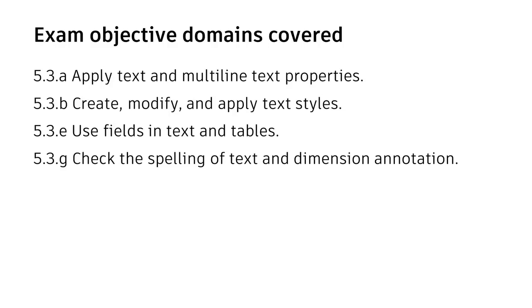AutoCAD also has some pretty nifty text features where you can leverage some of the existing data inside your drawing by inserting fields into text elements. We're also going to modify some text properties to adjust its appearance. AutoCAD has a built-in spell check and even allows users to add words to a custom dictionary.